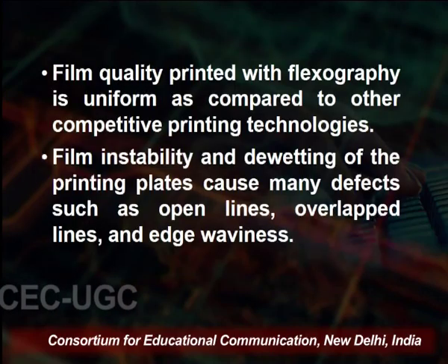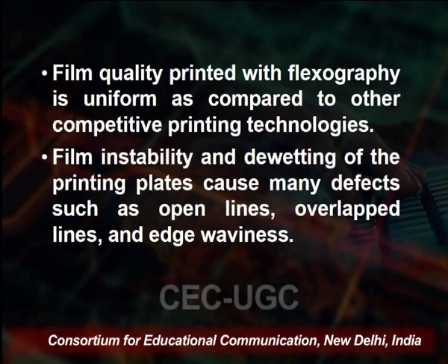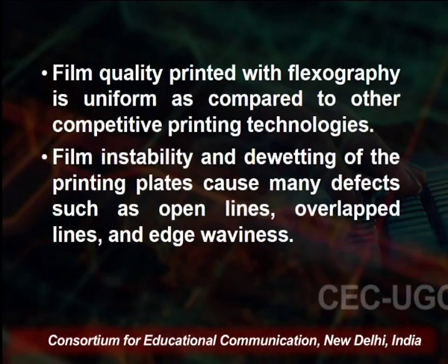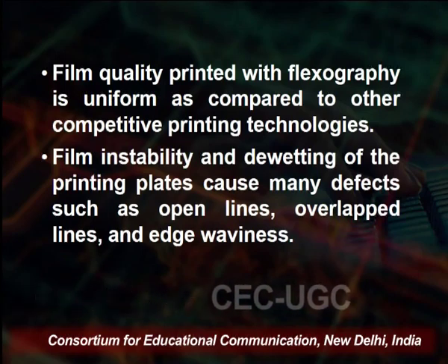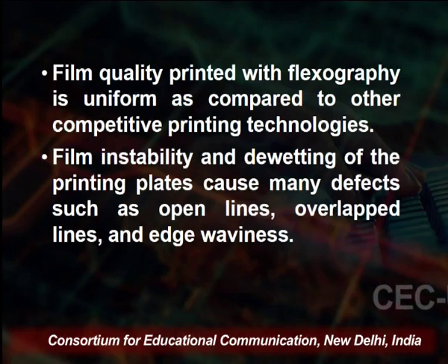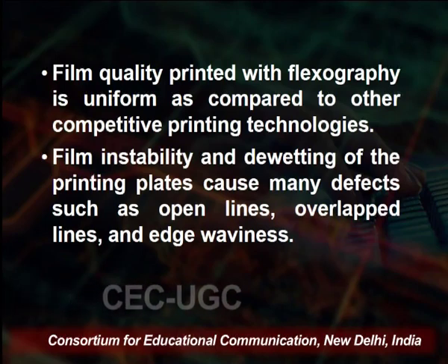Now, the film quality printed with flexography is uniform as compared to other competitive printing technologies. Film instability and dewetting of the printing plates cause many defects such as open line, overlap line and edge waviness. So, controlling the load pressure and the cell aspect ratio is very critically important to avoid these issues, especially in the case of targeting high resolution printing and high end devices.